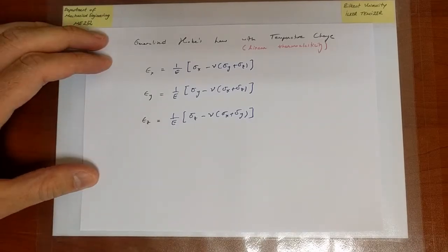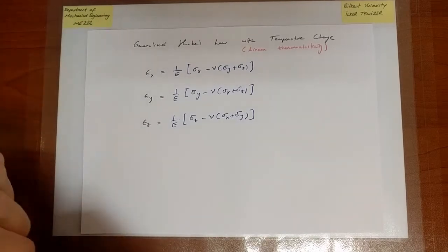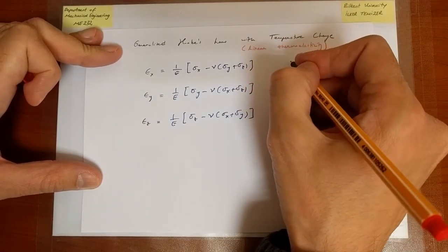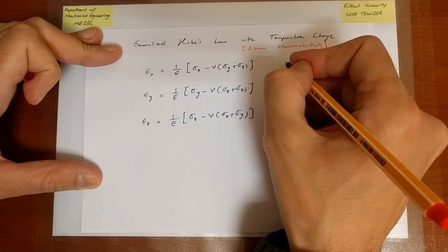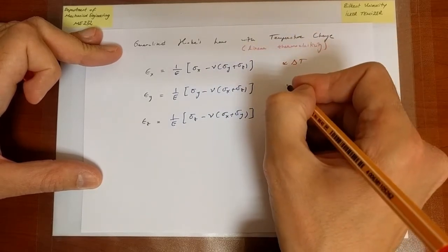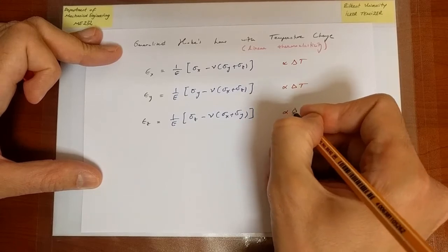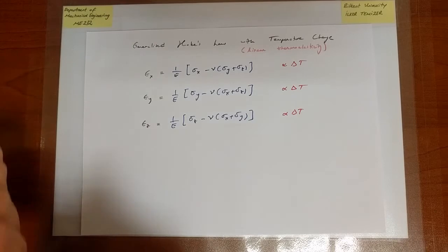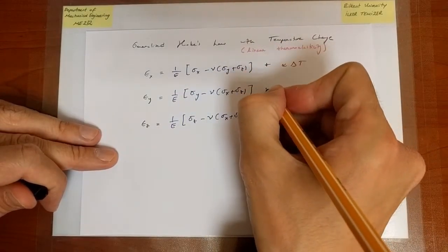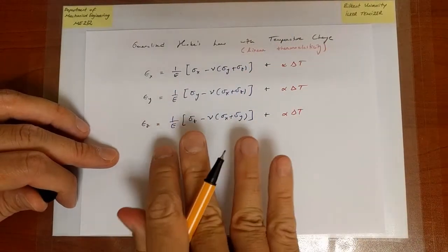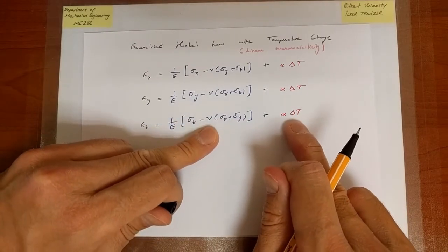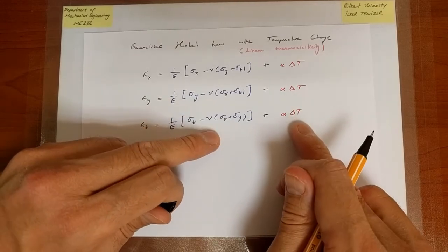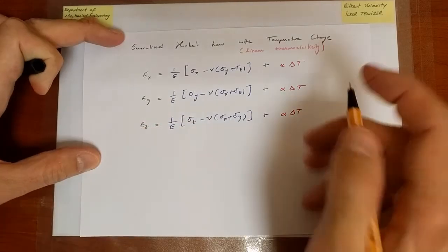And now, on the other hand, if we had pure thermal loading, then I just determined experimentally what we're supposed to do. We just get a strain that is equal to alpha delta T in all directions. And the question now is, well, what happens if I have both of them at the same time? Well, you just need to go ahead and apply the principle of superposition, individual solutions to two problems. And now if you have a new problem that is the sum of the conditions in the two problems, the solution is the sum of the solutions.